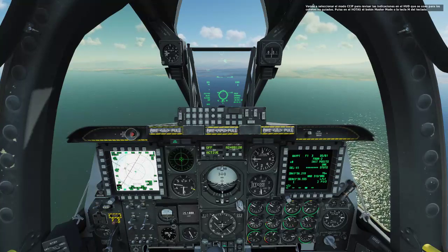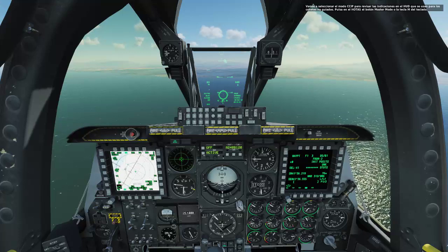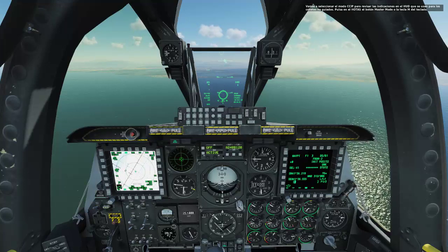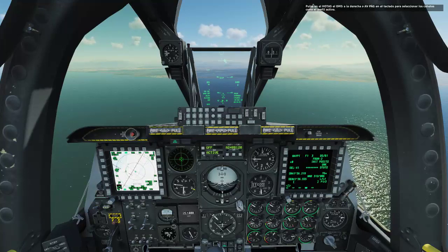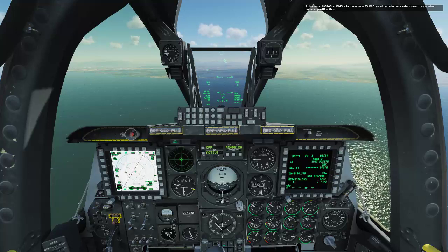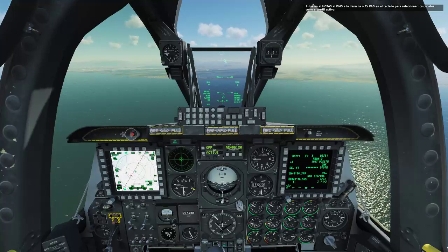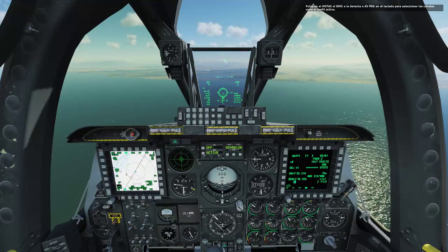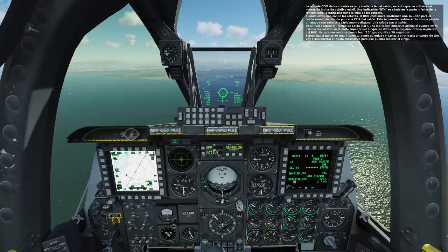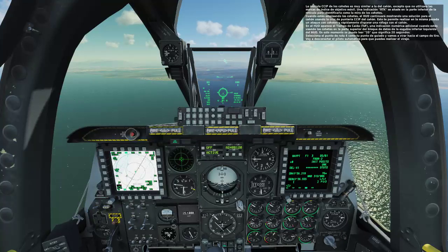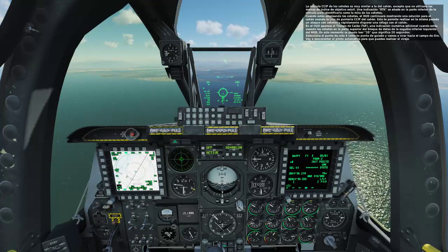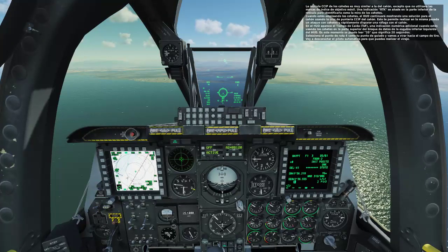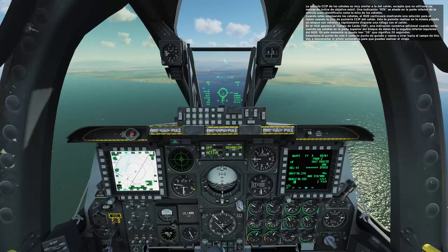Let's bring up CCIP mode to review HUD indication used for unguided rockets. Press the HOTAS Master Mode button once or the M key on the keyboard. Press the HOTAS DMS Right command or page down on the keyboard to select rockets as the active profile. The rocket CCIP reticle is very similar to the CCIP gun reticle, except it will not utilize the moving target index marks. An RKT indication is added to the bottom of the reticle to identify this as a rocket sight.